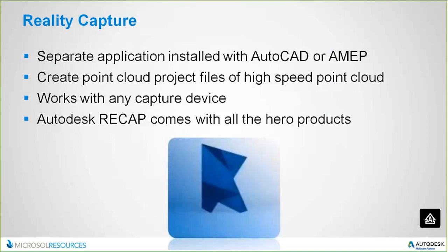So again, reality capture, that is something that comes with AutoCAD or AutoCAD MEP. It doesn't matter which product you have. It will be a separate installation, but when you install it, it allows you to bring in point clouds. A lot of people ask, what are point clouds? Basically, if you were to take a 3D laser scanner, set it inside a room or a facility, and let it run, it's shooting out a beam of light, and every point that it hits, it brings back information to the scanner. The scanner records it, and it gets these values built into it that allow the scanner, along with software, to produce a point cloud. So every point inside a point cloud file has value and distance and other information related to it, and that point cloud can be brought into AutoCAD, AutoCAD MEP, Revit, it doesn't matter, and you can actually see and touch and get dimensions off of these points.